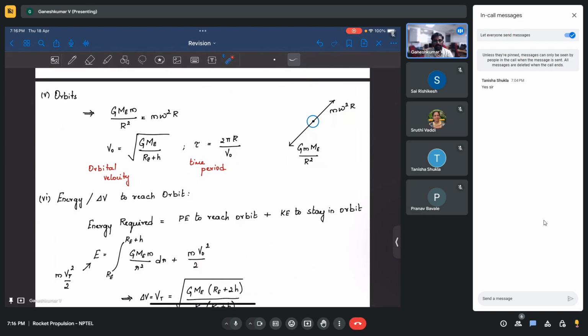After a certain amount of time, the orbital altitude will either keep on reducing or increasing, which we don't want. We want the satellite to stay in that orbit, so we do altitude corrections and attitude corrections to keep it stable in the orbit. That's why we have some thrusters and also fuel in the satellite. There we use monopropellant rockets, which we studied 2-3 weeks back, okay.